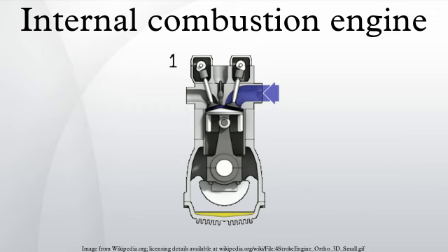A small amount of fuel is present after combustion, and some of it reacts to form oxygenates, such as formaldehyde or acetaldehyde, or hydrocarbons not originally present in the input fuel mixture. Incomplete combustion usually results from insufficient oxygen to achieve the perfect stoichiometric ratio. The flame is quenched by the relatively cool cylinder walls, leaving behind unreacted fuel that is expelled with the exhaust.